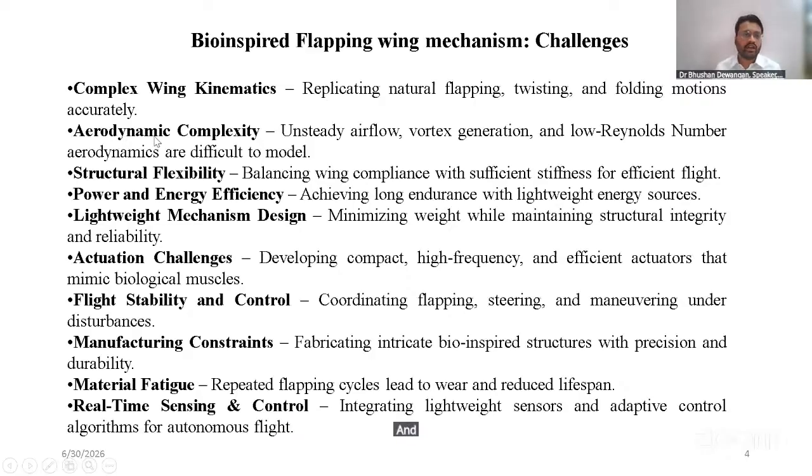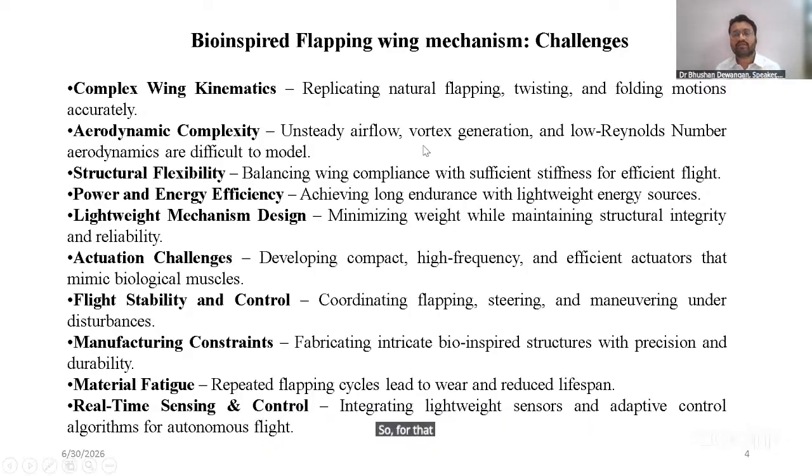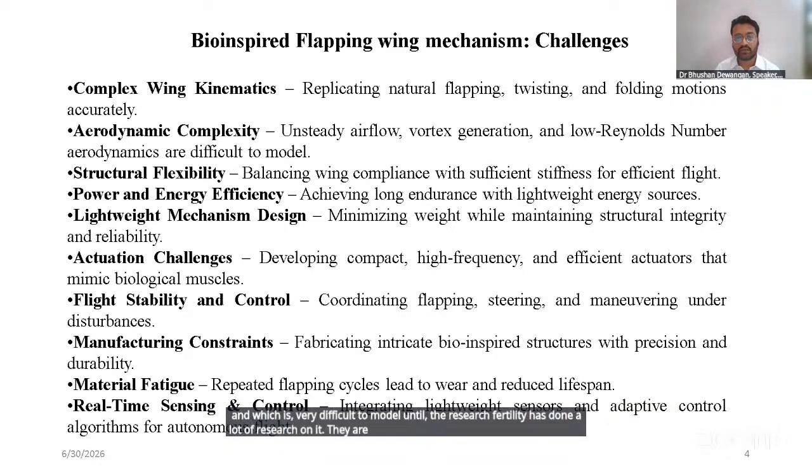Second is the aerodynamic complexity, because it works in unsteady airflow, and whenever flapping happens, vortex generation happens. This vortex generation is sometimes useful and sometimes not, so we have to compromise on these complexities. We will be working on low Reynolds number aerodynamics, which is very difficult to model. Still, the research fraternity has done a lot of research on it and is achieving good results.